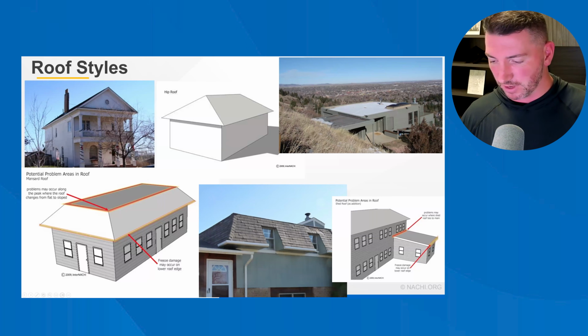There are two types of hip roofs, and both have four slopes. The basic hip roof has a level ridge, but the ridge doesn't extend all the way to the exterior walls. Instead, hip rafters slope diagonally to each corner. The hip rafters all meet to form a point at the peak of the roof.